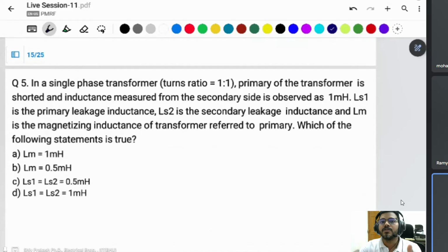Sometimes some circuits have a requirement of isolation. That's why they separate two circuits by ground, the common ground. If you don't want a common ground between two circuits, and you want the output side not to affect the input side, then you use an isolation transformer, like in the gate driver of a MOSFET and IGBT. There is a requirement of an isolation transformer there also.